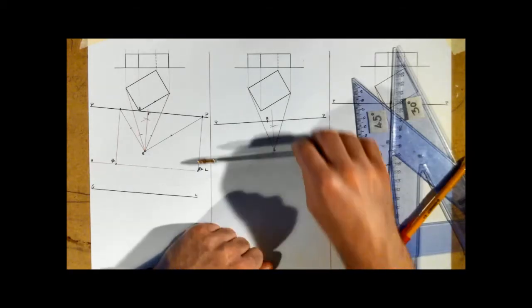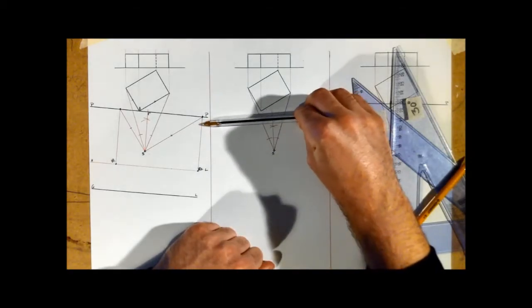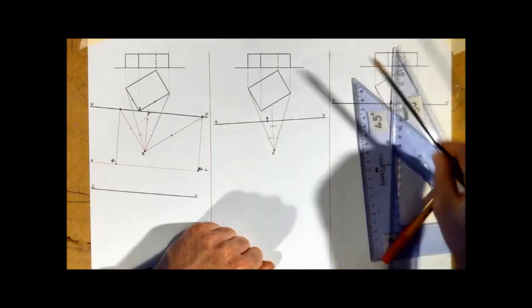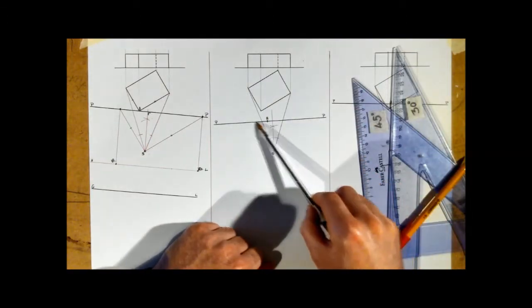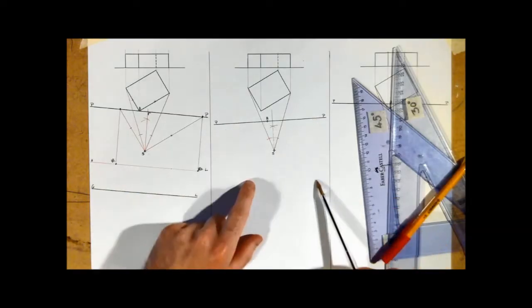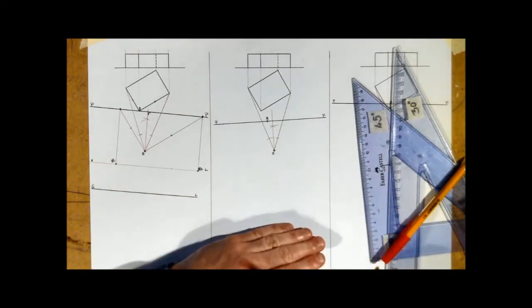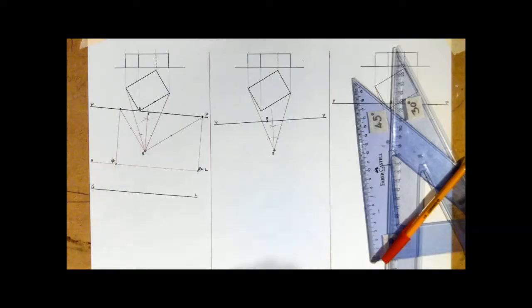So, going to do the exact same in this question here. And in this question here, I'm first of all going to go parallel to the extreme edges to locate obviously the positioning of my vanishing points, where I'm going to drop them down, and then I'm going to set up my ground line and horizon line as well. So I'm going to speed that up there now once again.